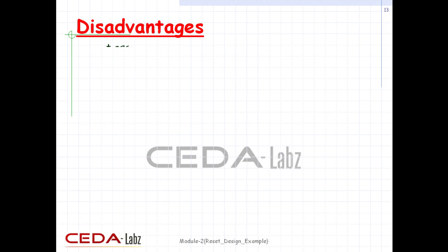The problem in this topology is with reset assertion. If the reset signal is not long enough to be captured at the active clock edge, or the clock may be slow to capture the reset signal, it will result in failure of assertion. In such a case, the design needs a pulse stretcher to guarantee that a reset pulse is wide enough to be present during the active clock edge.